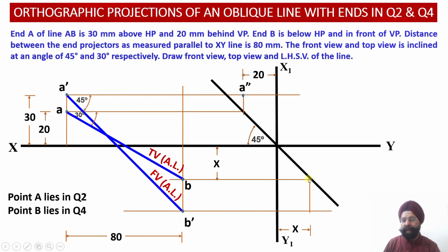So over here, we have obtained a point corresponding to the plan projection point B. And from this point on the transfer line, we are going to draw a vertical projector in the downward direction such that it intersects with the horizontal projector which we had drawn from the elevation projection point, that is B dash. Wherever these two projectors intersect, we get the location of the point B double dash over here.